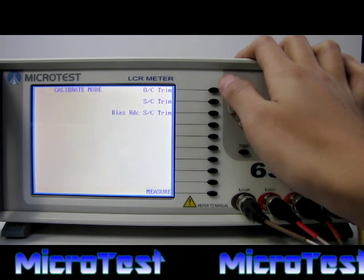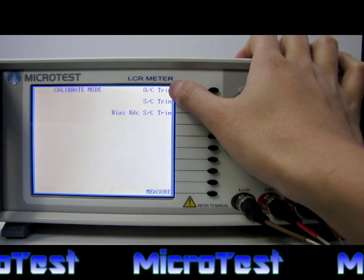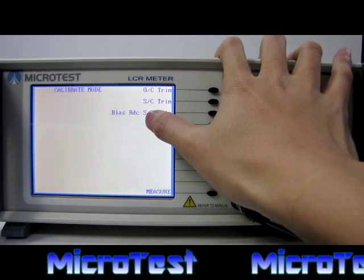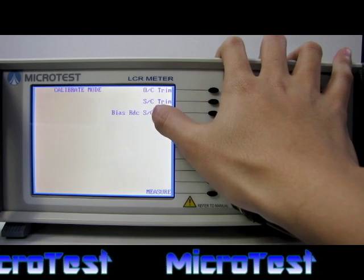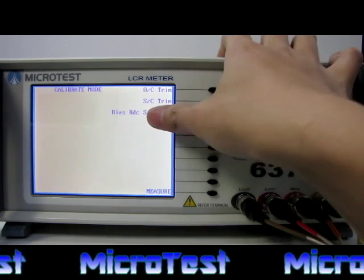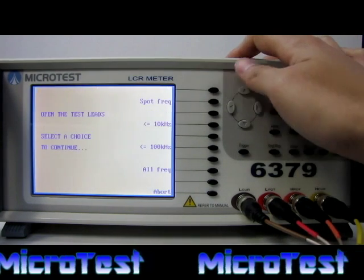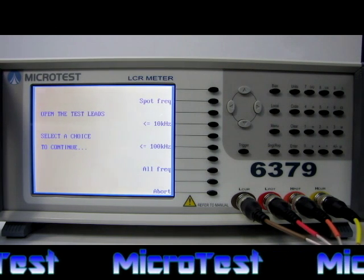There are three functions: OC trim for open circuit, SC trim for short circuit, and bias RDC SC trim for use when attached with DC bias current source. When using only the LCR meter, it is unnecessary. We will start with the OC trim. We can calibrate specific frequencies or all frequencies.